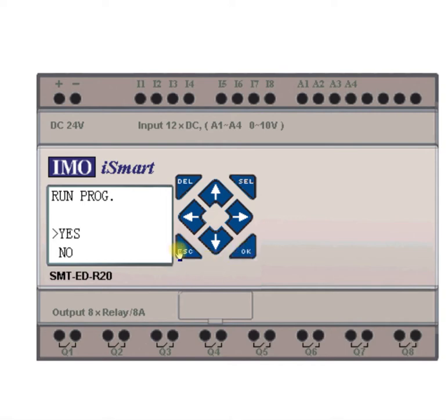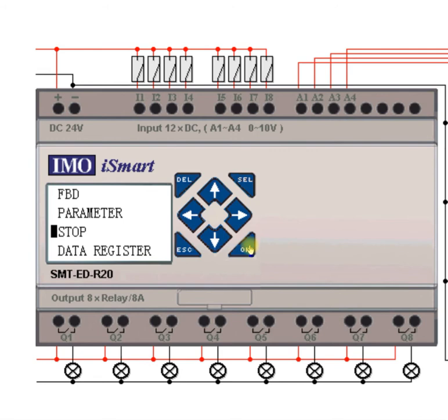and escape. Now one thing you might notice when we do this, let's do this again. We're going to say run, OK, and we want to go up to yes and say OK. Now you notice it comes right back saying stop. That's asking you if you want to tell it to stop. That's not in the stop mode. You can see that everything's live now, and if we escape back to our I/O screen, it's now in the run mode. So this loader would be actively running.